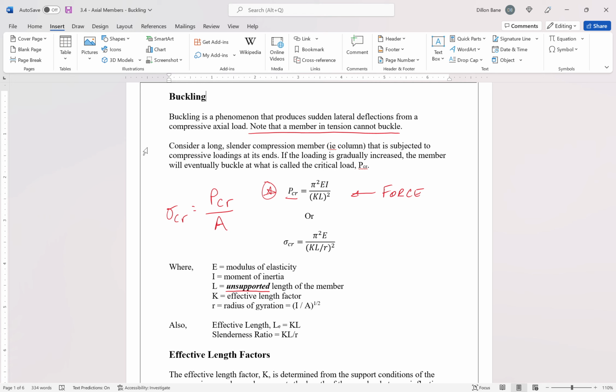Well, what if you were to take that paper clip and cut it in half and only try and get half of that paper clip in between your fingers and try and get the same buckling effect out of that? You will find that it is much harder to buckle that little shorter piece of wire than it is to buckle the longer piece of wire. Intuitively, this might make sense to a lot of you, right? So the longer something is, the easier it is to get it to bow and to get it to bend out like that under a compressive load.